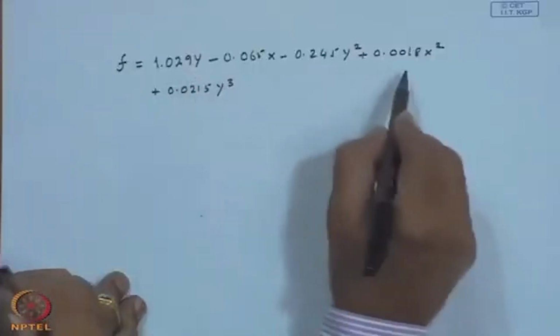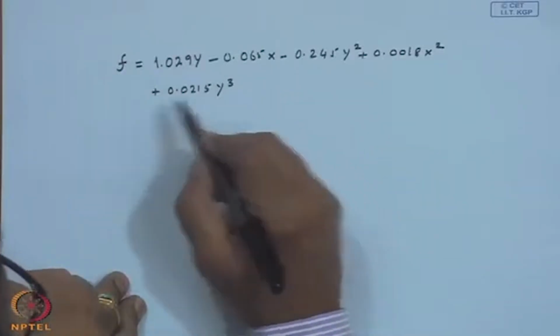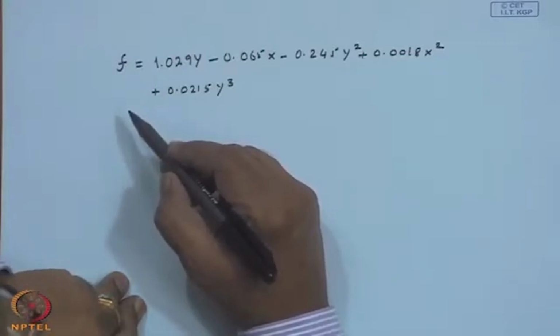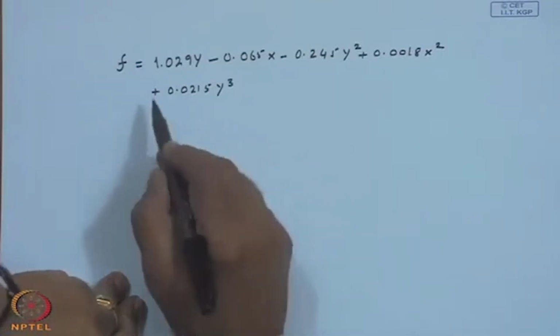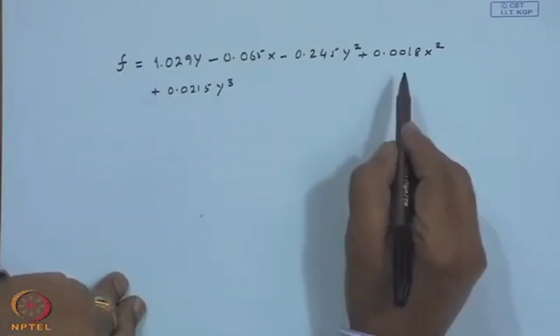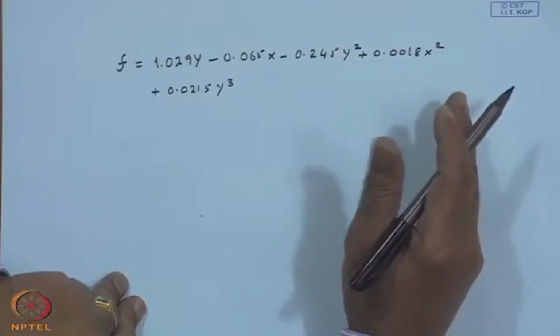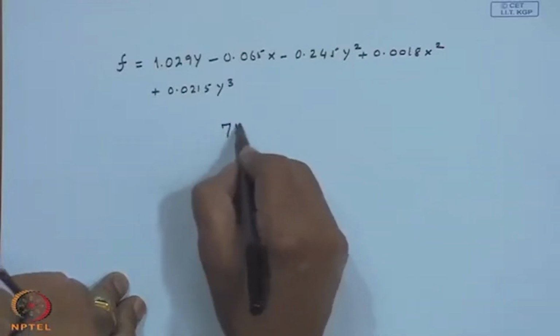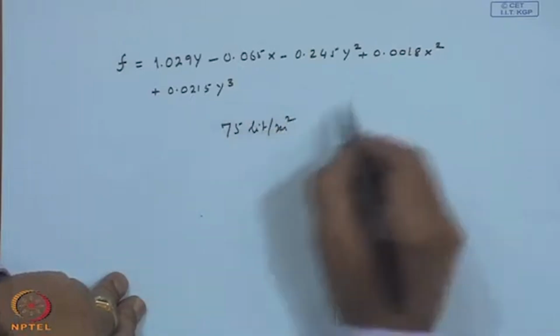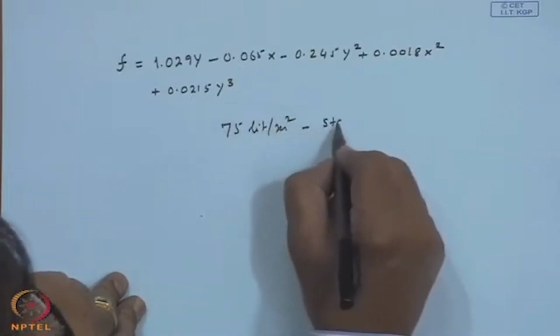However, the slight difference between air and liquid based systems comes mainly from the storage and the heat exchanger effect. In addition, you will find that liquid based systems have a certain volume of water, like 75 liters per square meter of collector area, as the standard storage.